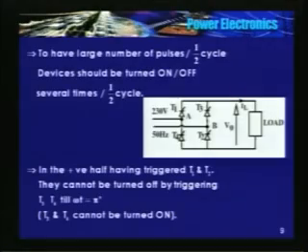See this figure, in the positive half you have triggered T1 and T2, potential of A is higher than potential of B in the positive half. So when T1 is conducting, cathode potential of T3 is the same as potential of A, and a negative voltage appears across T3 in the positive half.